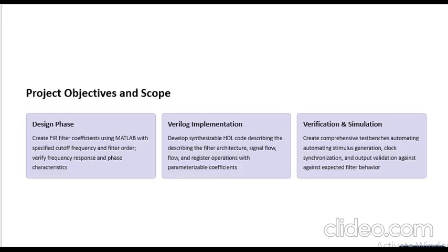We primarily used MATLAB's signal processing toolbox, which offers comprehensive tools like fir1 for window based FIR filter design. We configured a bandpass filter to target the diagnostically relevant frequency range of ECG signal, specifically between 0.5 Hz to 40 Hz.